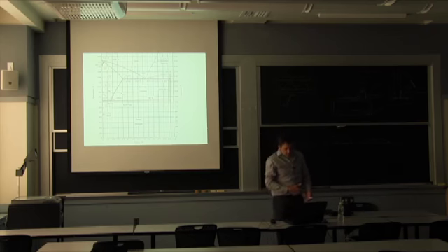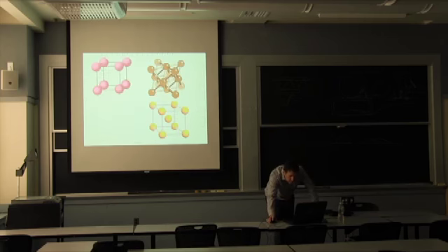And what that means in practice is you have a face-centered cubic structure. And I should show it right now. So this is this one. That's what you get in that austenite zone. And as you continue cooling with steel, you become a body-centered cubic phase. That's the yellow one here.